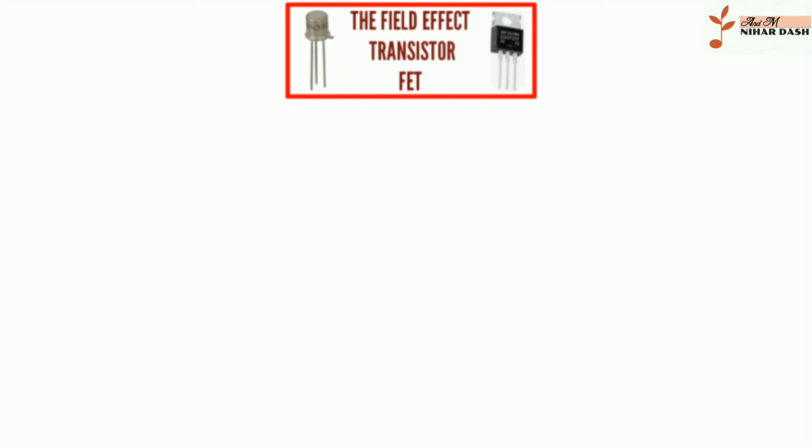In this application, FET circuits consume much lower levels of power than ICs using bipolar transistor technology. This enables very large-scale integrated circuits to operate. If bipolar technology was used, the power consumption would be orders of magnitude greater, and the power generated far too large to dissipate from the integrated circuit. Apart from being used in integrated circuits, discrete versions of field effect transistors are available both as leaded electronic components and also as surface mount devices.